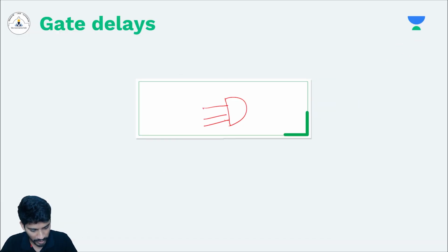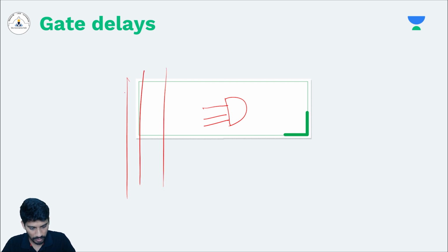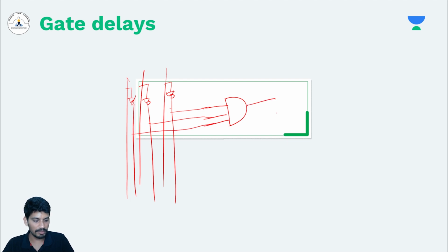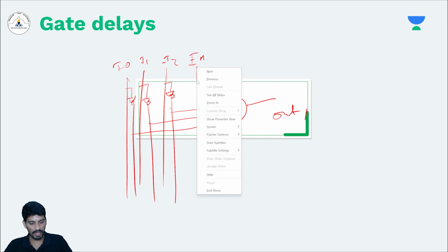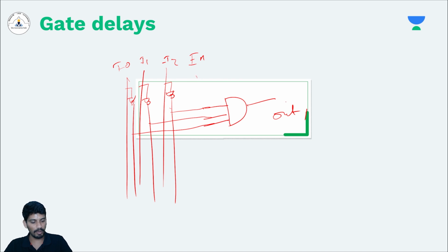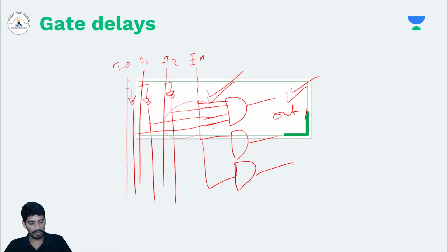Beforehand we have a decoder like this and these are coming through the inputs. So this is mapped to the 0 0 0 case. This is my out 1, and these are my I0, I1 and I2. I want to add one more extra signal called the enable signal. Whenever this enable is equal to 1, then only I want my output to appear. So I have to connect this enable to all of these AND gates. What this means is, when the enable is 1 then only this will execute and pass the output through.